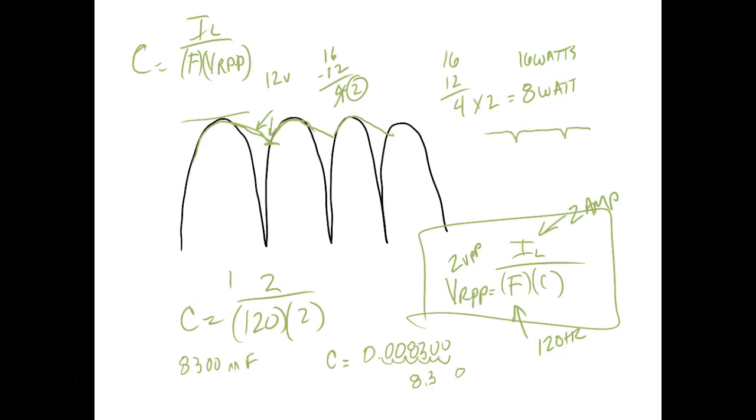Yeah, I recommend they put batteries. You have a big old battery back there. Of course, batteries cost a lot of money too. And then you have to consider 1,000 watt output. It depends on the efficiency of the amplifier. So you need to check, because there's no amplifier that's 100% efficient, right? Y'all understand that? So that means if I get 1,000 watts out, I probably have to put at least 1,500 watts into it, and that's your power in your system.